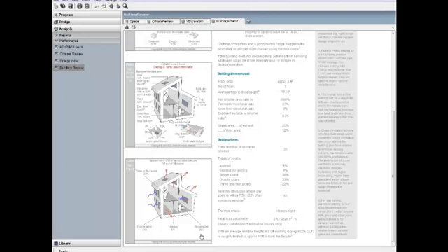Using Affinity+VE, we can analyze the building, and if the location has a hotter climate, for example, we can create a department-level program requirement to make sure that the high heat gain areas avoid direct sunlight. For instance, we could create a requirement in Affinity that says IT departments must be on the north or south side of the building. By using these analyses to specify properties for the building and departments, project teams can use the requirements to guide the design, ensuring optimal sustainability.